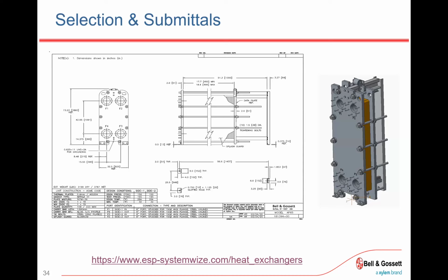Moving on to the next thing, if you need an air separator, you can say I want a centrifugal air separator. It already imported the last flow rate because you're doing it for that system. You do a search, see the RL5F, you select, add an air vent. So it kind of walks you through a lot, and I'm sure a lot of it is just trying to get the sale of everything, right? Once you select one item, it does make it easier, and I guess might as well, rather than trying to figure out what automatic air vent goes on that air separator, or what blowdown valve would fit it.